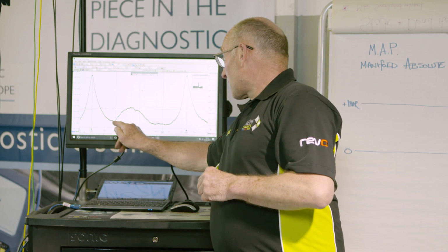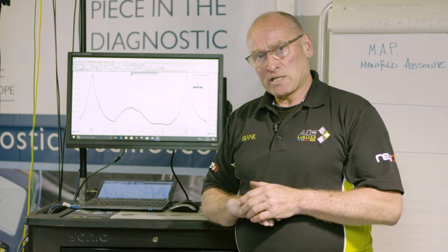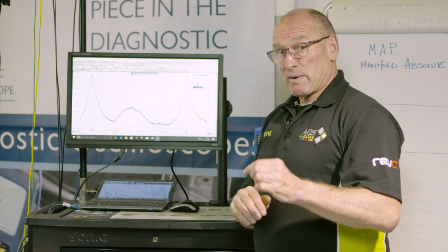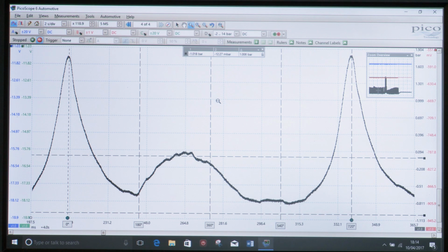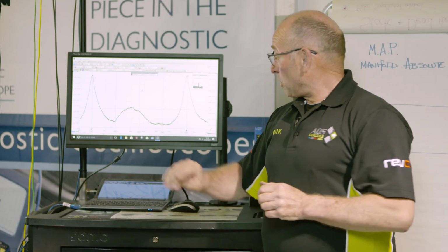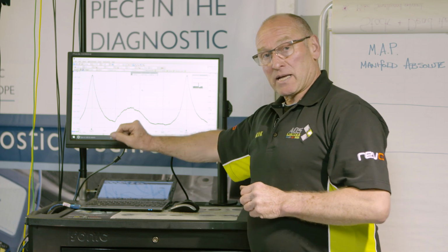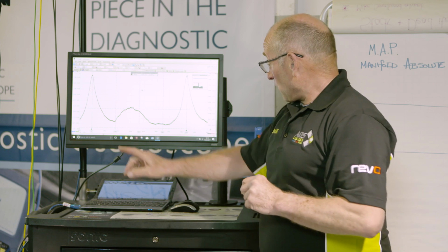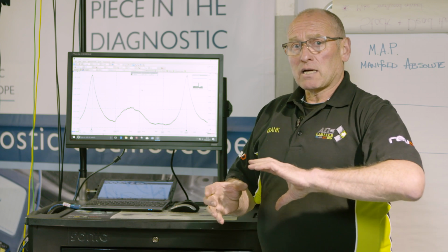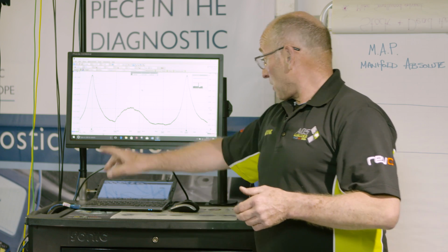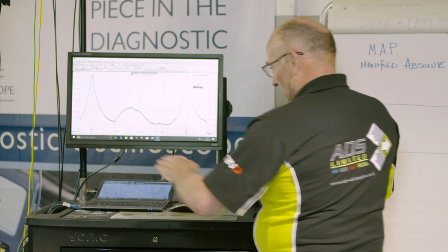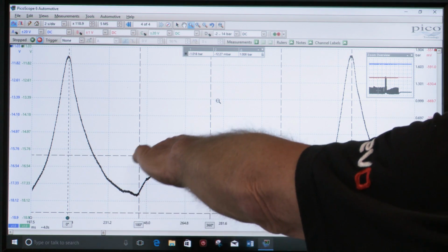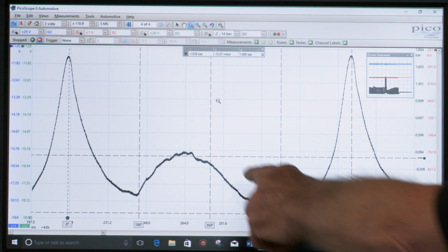And the answer is the exhaust valve has opened. So we now can prove exactly when the exhaust valve has opened. So why has the pressure gone up? Pressure differential, because in the exhaust stream, the pressure will be higher than it is down here. Pressure differential, you're going to get flow. So it's actually going to draw in a little bit of exhaust gas at the bottom of that stroke. It has to. Pressure transfer. Then the piston starts to move back up the bore, up to TDC.